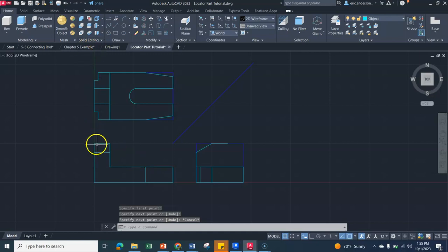All right, now the pain in the butt is going to be that weird little cutout notch that's going over here, because it ends somewhere in that spot. So let's just sketch it out from my front view. I'm just going to put a perpendicular line all the way over there, but I'm not quite sure where it lands over here. But if I use my miter line, that might give me some extra information. So I'm going to find where that ends.